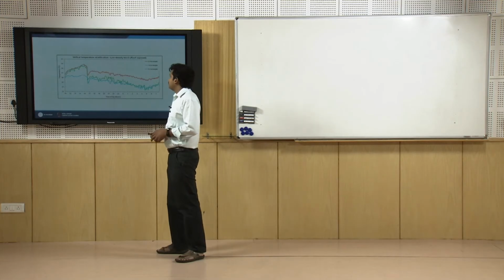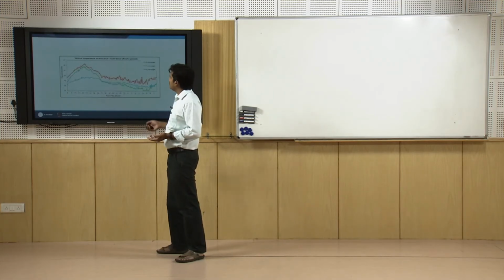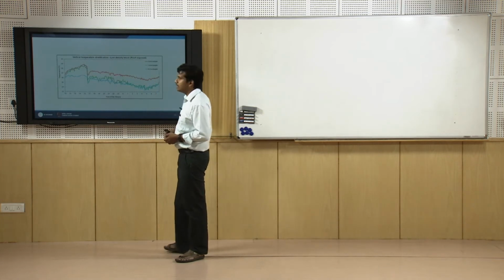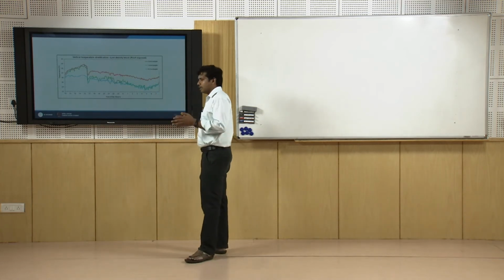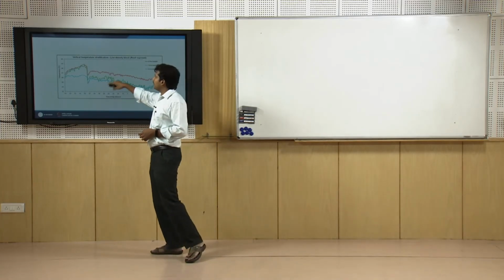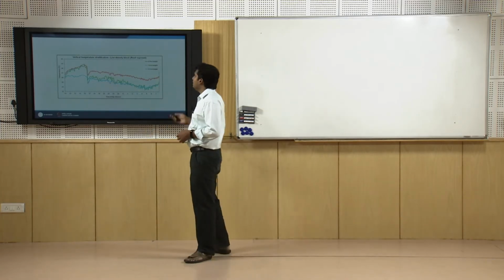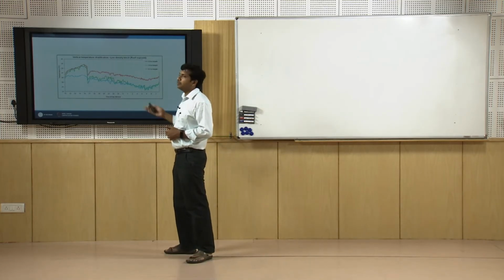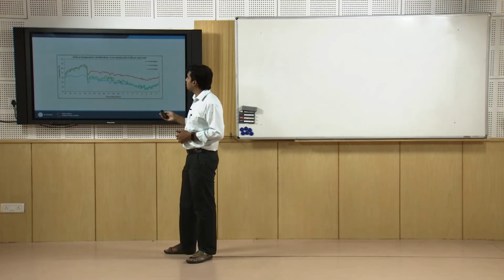It also depends slightly on the material used. The earlier one was solid cement block, this is like a low density block, it can be an aerated concrete or a hollow wall, a cavity wall system. Even there you will find the vertical temperature difference, it will be considerably different from one material to another, the magnitude may be different but the pattern of variation remains the same.